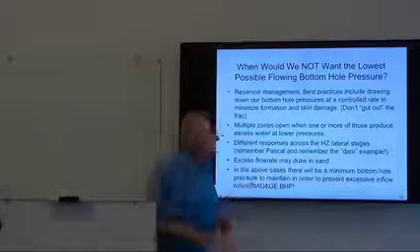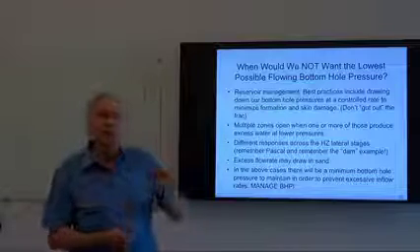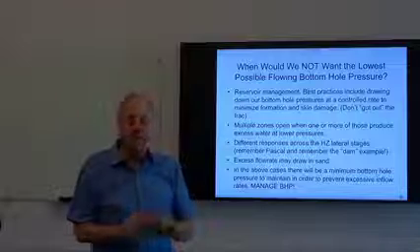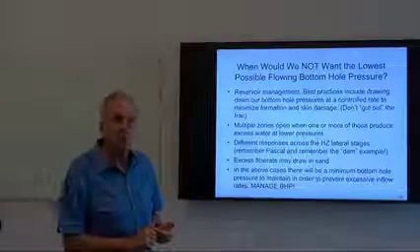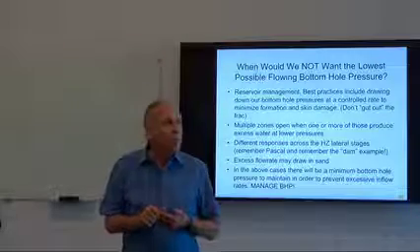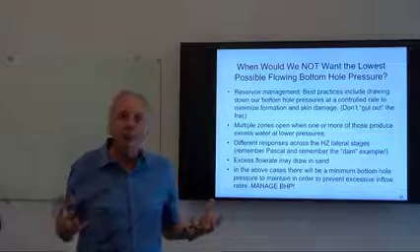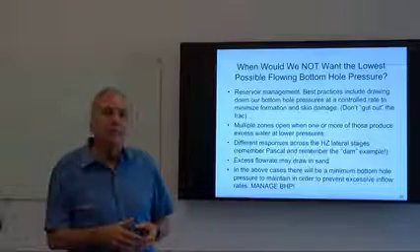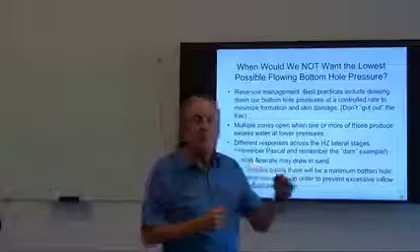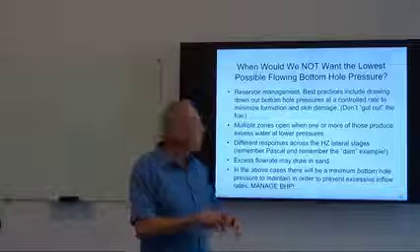Another is where they're in vertical wells in particular, where we have multiple zones over an interval, and they may have different gas to liquid ratios for those particular formations. They may also have their own, let's say, threshold pressures at which they hold back liquids and below which they release liquids. So we have to be very careful as we pull our pressures down that we don't pull them down so fast that we flood the well out.